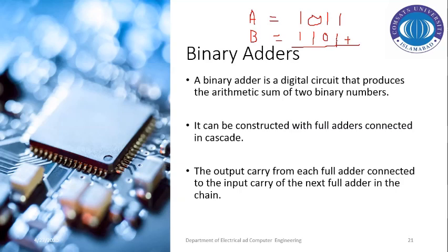We can use a half adder to add those two binary bits, or we can use a full adder with the third input set by default to 0. So 1 plus 1 equals 0 with 1 carry. Now, in this case, for the addition at this specific placement, we require a full adder. A half adder is not sufficient because we've got three binary bits here to add. So 1 is added with 1, and then the result is added with 0. So 1 plus 1 equals 0 with 1 carry, and 0 plus 0 equals 0. The sum result is 0 and the carry result is 1.